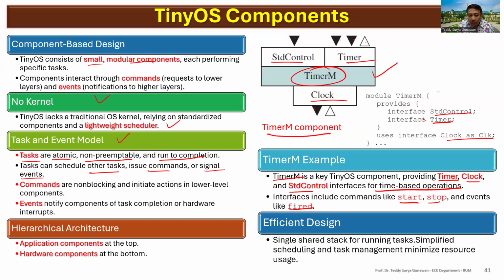We have tasks and we have commands. Commands are non-blocking and initiate actions in lower-level components. And the last one is events. They notify components of task completion or hardware interrupts. So you have the tasks, the commands, and the events.